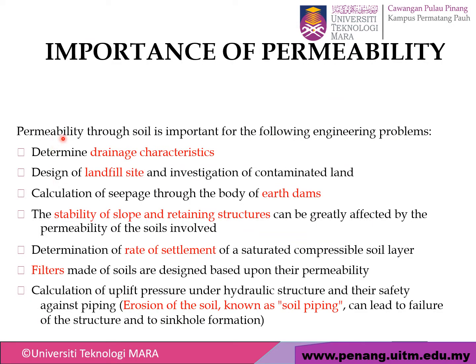So permeability through soil is important for the following engineering problems, because we want to determine the drainage characteristics, design a landfill site and investigate contaminated land, and calculate the seepage through the body of a dam. The stability of slopes and retaining structures can be greatly affected by the permeability of the soil involved. Determination of the rate of settlement of a saturated compressible layer.